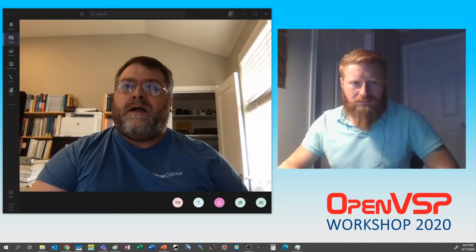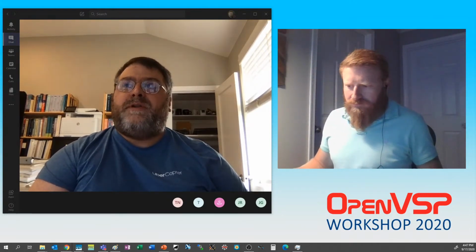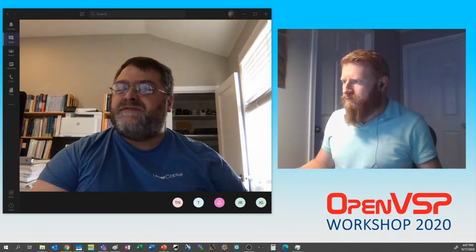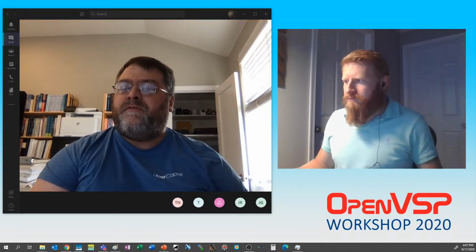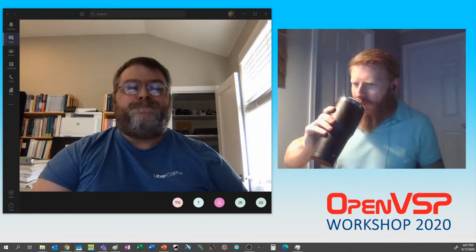There's a NASA publication by Harris that is a compendium of hover test stand data for props and rotors that includes a lot of those different steps in the XV15 rotor and specifies the foils used in them. So I recommend you look for that report by Harris. The early ones used, like I'm saying here, a 1.6 series and 6.5 series. The later ones went to proprietary airfoils that were developed by Bell.